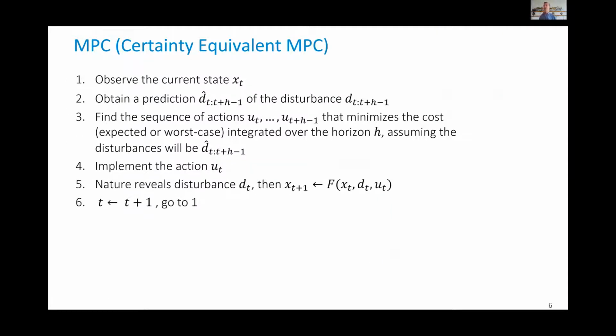Then here is really the code of how an MPC works. We do a loop, so we repeatedly do the following thing. We must run this loop whenever we want to compute the next state xt. So that must run fairly fast, in a matter of seconds. Then we will do nothing until we get more information. And for example, if we compute a new set point every 5 minutes, we will run the sequence of operations every 5 minutes. So at every execution of this round, we observe the current state.